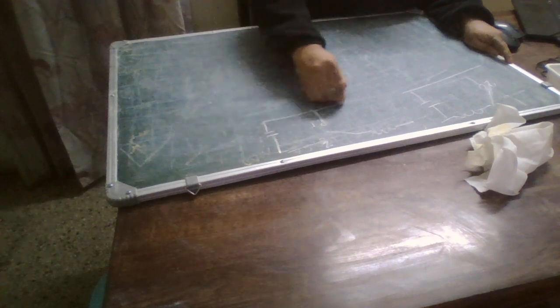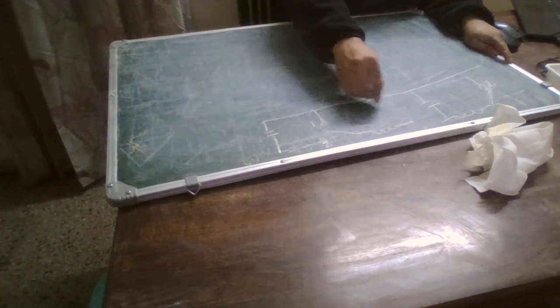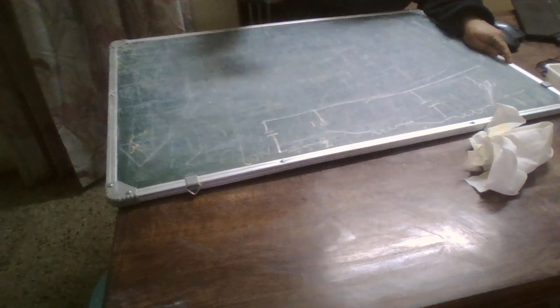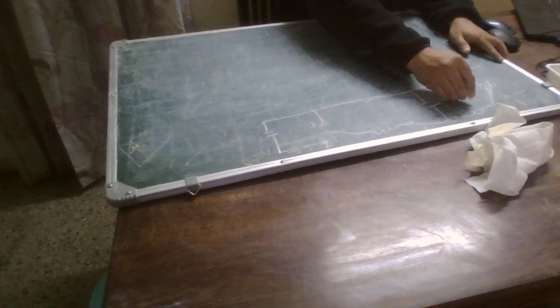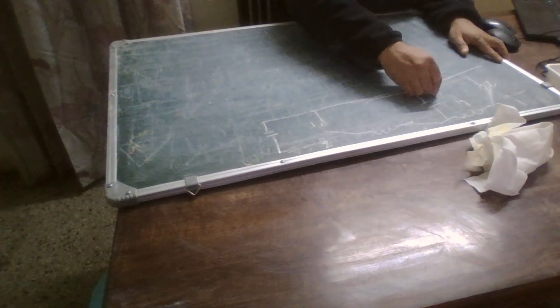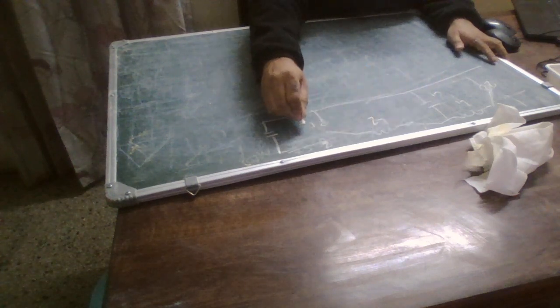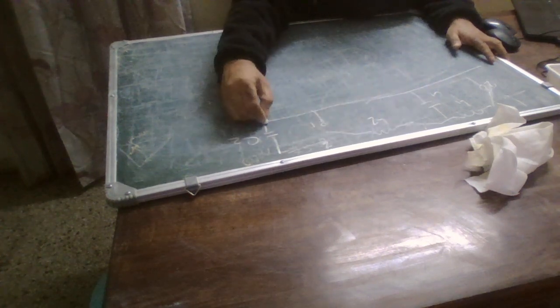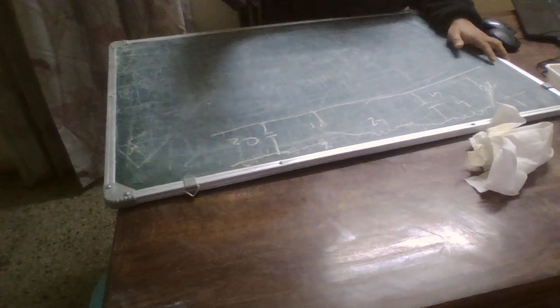Now we are just connecting them, and this forms a buck boost converter, basically a non-inverting configuration. You can see very easily here that we can denote L1, C1 for the buck converter, and L2, C2 for the boost. I have only attached them, I haven't made any changes yet.